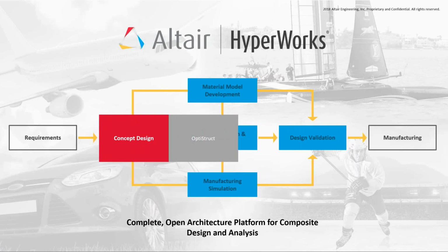The main tool for that part is our FE solver OptiStruct, which has very special optimization capabilities built in. Basically, for composites, we can start from a topology type of approach to find the optimal load paths to carry the loads on the structure, and then go further into designing the ply shapes to be optimal for carrying the loads.